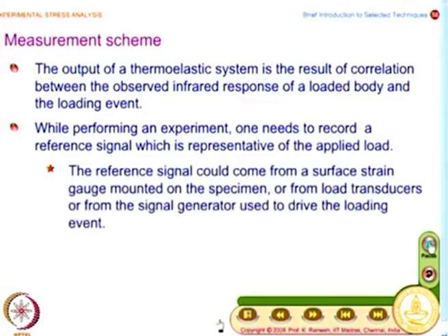What I find here is that the reference signal could come from a surface strain gauge mounted on the specimen, or from load transducers, or from the signal generator used to drive the loading event. So, I need a reference signal, I need to have a correlation between the loading event and the recording phenomena.